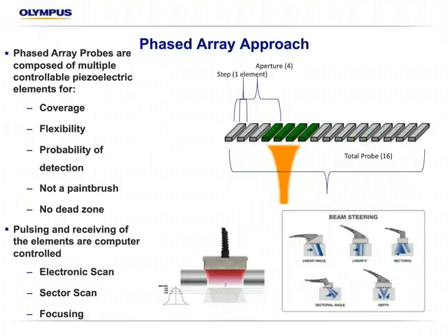And typically this is the normal approach for detecting corrosion, 0 degree, as it always has been, even when we go to phased array. But phased array does offer the benefit of the flexibility of steering the beam, so we could actually change that to 45, 60, 20 degrees, depending on what we're looking for, and we could have it rastering at that angle at the same time, depending on which probe we're using. Or we could do a multi-angle sweep of beams in order to detect off-axis defects, some of those unique damage mechanisms like stress corrosion cracking and H2S that might be oriented at different places, or any other given angle.